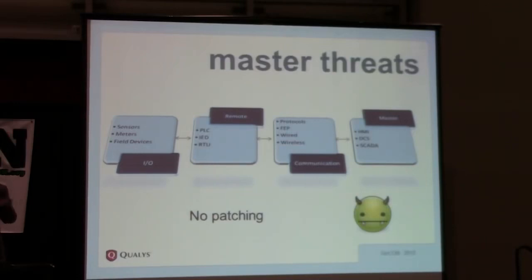One is your operating system vendor, which could be Microsoft or Linux or whatever, and one is your SCADA software vendor. If the SCADA software vendor doesn't give you enough guidance on whether this patch is safe to apply or not, as a SCADA engineer managing that system, what will I do? When Microsoft releases a patch, will I just go and patch the system because I want everything secure?